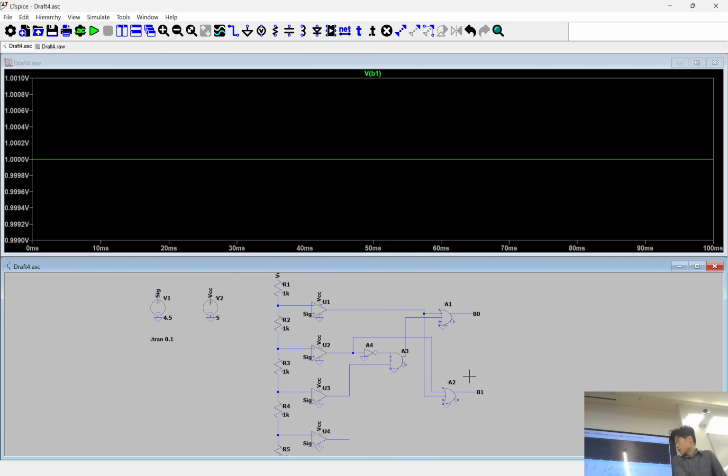So I've configured up some logic gates. I'm not going to talk too much about those itself or the logic behind it. But we can experiment with a few different values now. So let's say we have 4.5 volts. And between the reference points, so we had reference points 4, 3, 2, 1. So 4.5 is greater than all of those. It's going to give me all ones. And the greatest possible binary number for that is just going to be 1, 1.